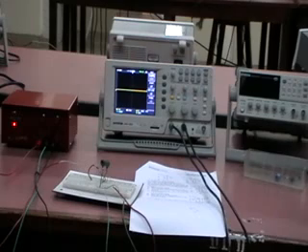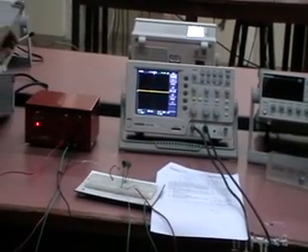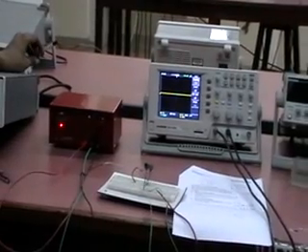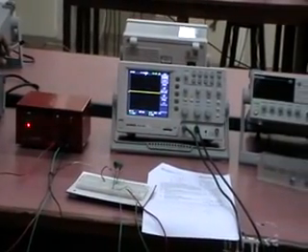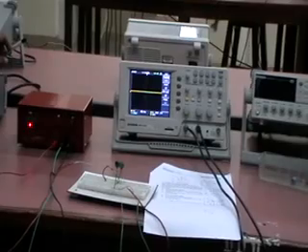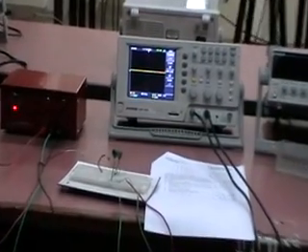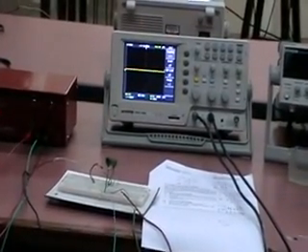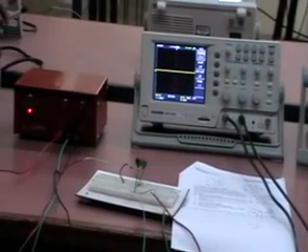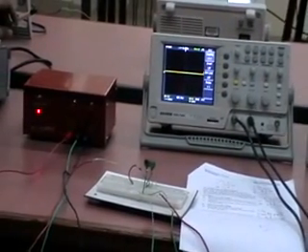Before starting this experiment, we should take some precautionary steps before connecting the circuit. The circuit that we are going to connect will provide enough power to heat some components and burn them or even blow the fuse. So we should be extremely careful and ensure that your wiring is correct. There should not be any loose contacts, and all the contacts should be firm. At no point in the experiment should the outputs of the transformer or the rectifier be short circuited. So these are the precautions that you should take.